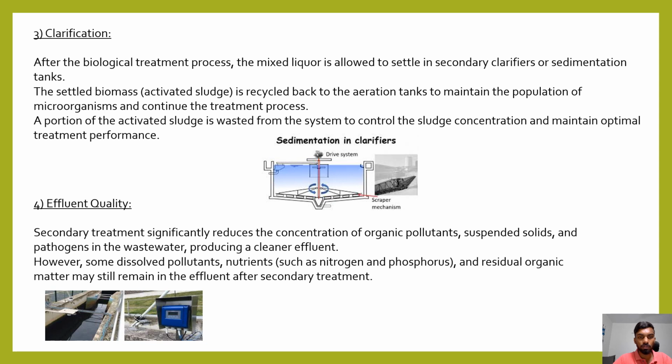Secondary treatment significantly reduces the concentration of organic pollutants, suspended solids, and pathogens in the wastewater, producing a cleaner effluent. However, some dissolved nutrients and residual organic matter may still remain in the effluent after secondary treatment.